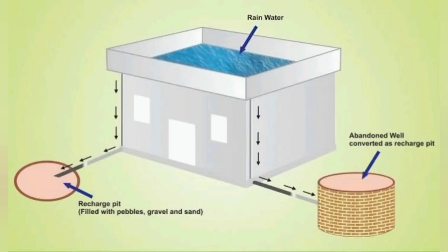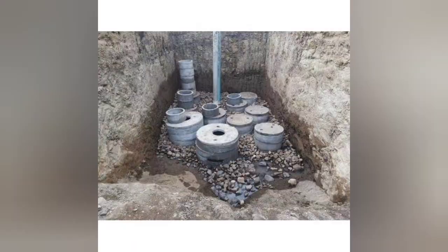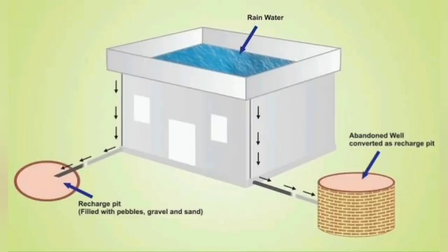In order to know the infiltration rates of soil, infiltration tests are carried out. Cylinder or flood infiltrometers are common types of instruments which measure the infiltration as the rate of water leaving the device. Maps showing the infiltration rates of soils are prepared. These help in designing suitable artificial recharge structures and also in assessing the extent of recharge from these structures.